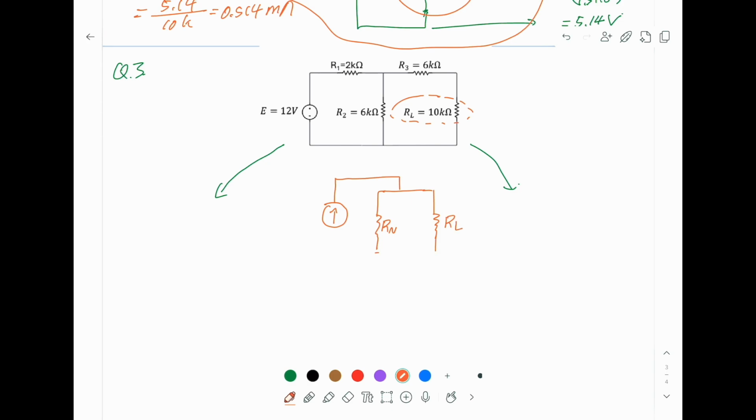So this time we use a current divider instead of voltage divider. It divides the current into two paths. And from here we can find the voltage and the current passing through RL. So from this point of view, the Thevenin approach and the Norton approach, they are equivalent. Now we want to find this current source, therefore we call this I Norton. Okay, so this is our ultimate aim.